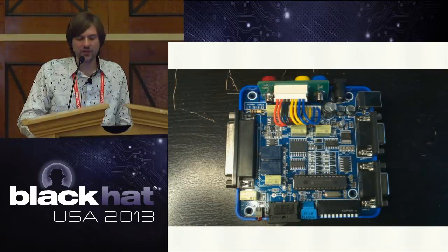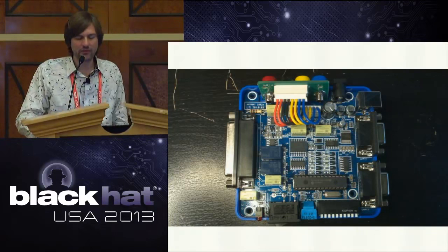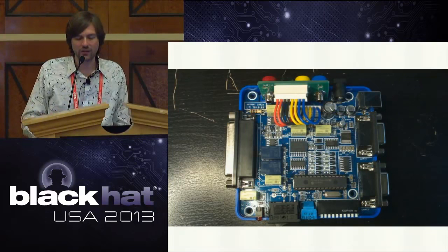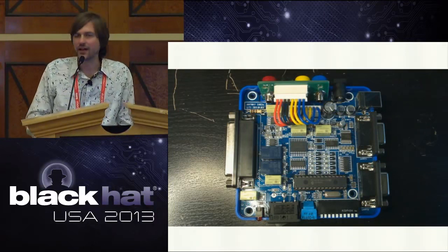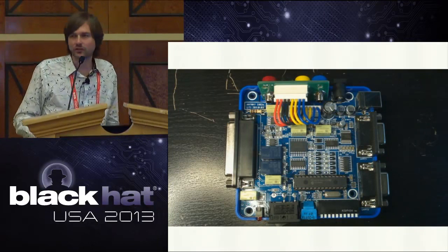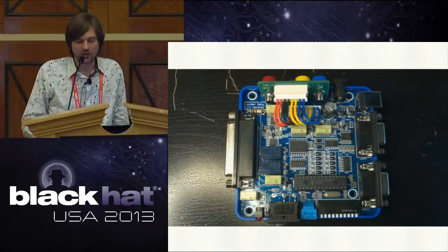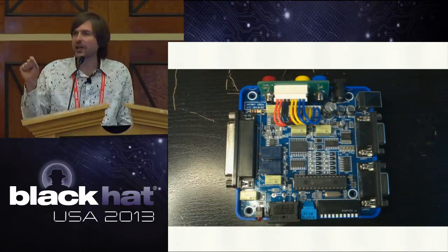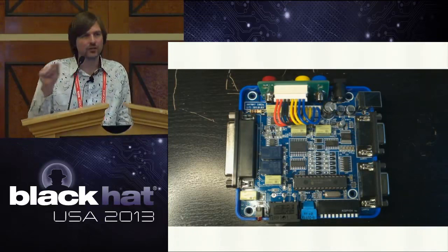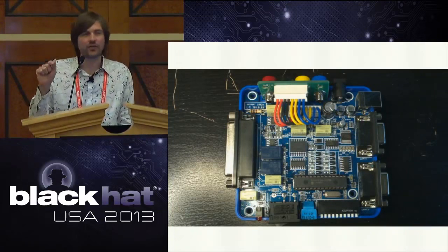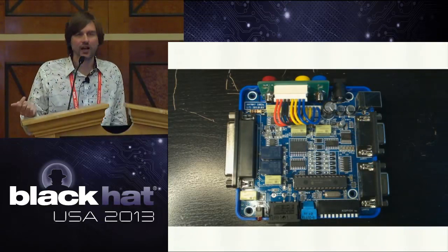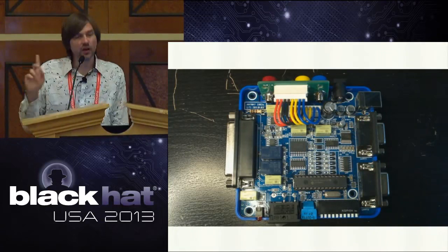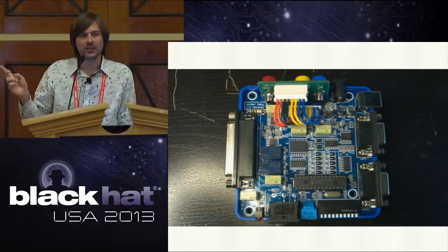And then just above that long DIP package microcontroller, there's a grid of surface mount parts that includes a bunch of fixed resistors. You can't read it from there, but with my magnifying glass, I could read the values off those resistors, and sure enough, there were several values that corresponded to the table of values commonly used for those multiplexer ICs. Interestingly, 150 kiloohm is not in this.